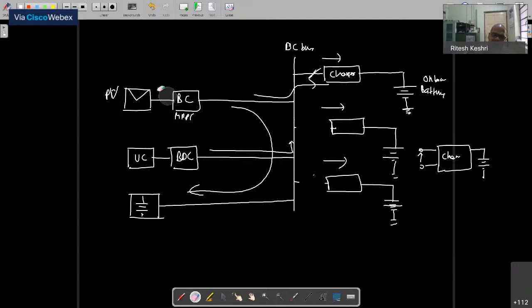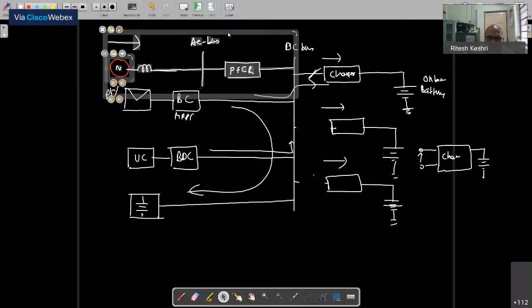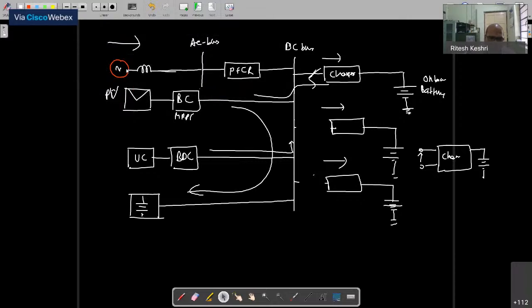So this is a PV fed battery assisted or ultra capacitor assisted charging station. But of course, let's suppose that you have energy storage, they also fail sometimes. So maybe you want to use the facility of the grid. So it will be a PV fed grid assisted charging station. Grid assisted means you will not be using the grid for all the time, and maybe during the night time you will be using it. Or maybe you will be using the grid together with this battery energy storage.